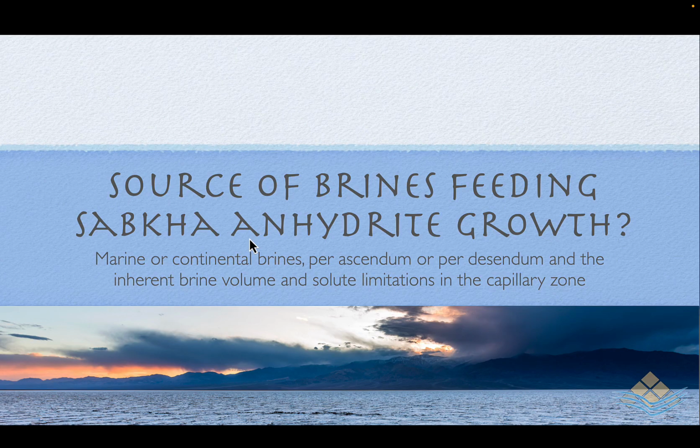And we'll also consider the hydrological implications in terms of the inherent brine volumes from various sources and the solute volume limitations in those capillary salt growth zones within the capillary zone, tying it back to the notion of, are these prograde or retrograde salts forming in that zone of capillary evaporation?